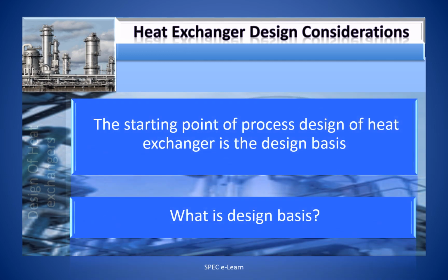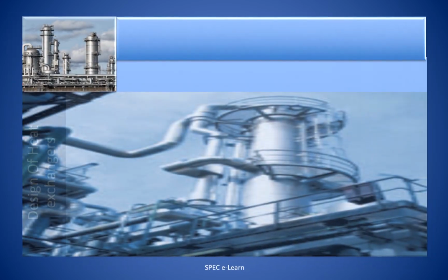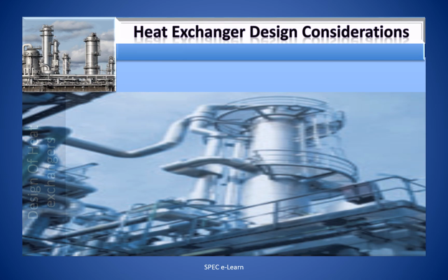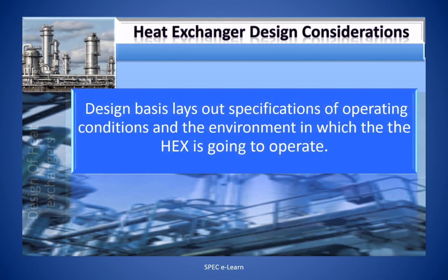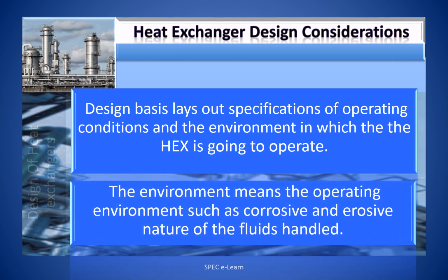The starting point of process design of heat exchanger is the design basis. What is design basis? Design basis lays out specifications of operating conditions and the environment in which the heat exchanger is going to operate. The environment means the operating environment such as corrosive and erosive nature of the fluids handled.